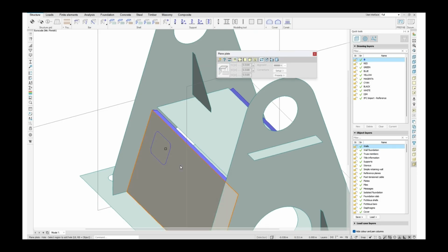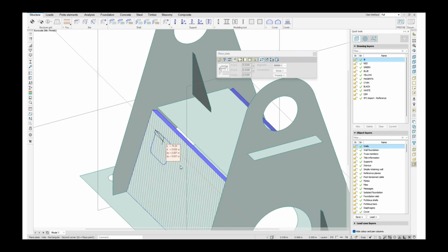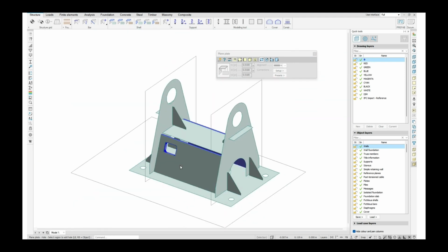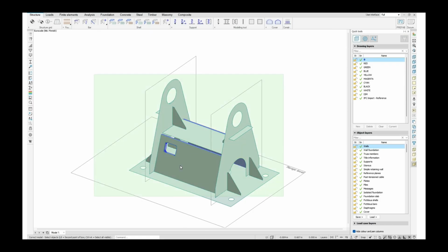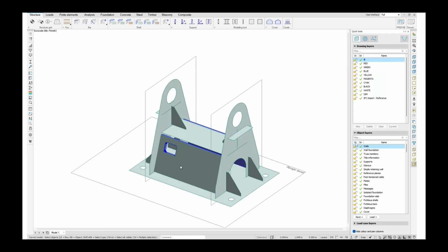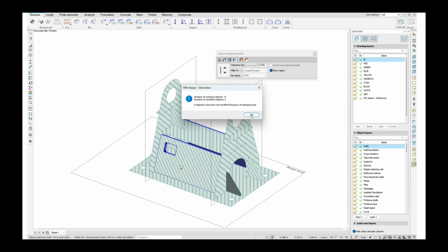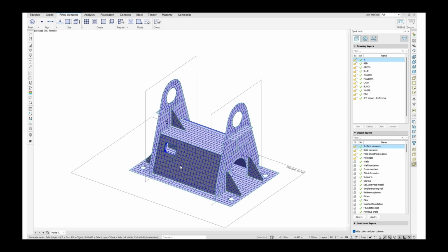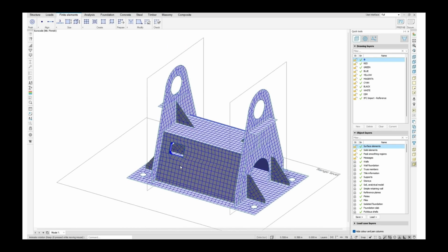The only thing missing is that we have to put the hole and fillet for the hole, but I just make a square hole here. And then all we need to do is to use the correct model. So we stretch to these 4 references, and then we connect shell models together to make it work like this one. Adjust the analytical model and connect them together, and then we get an almost perfect finite element model easily. It doesn't take long to do this.